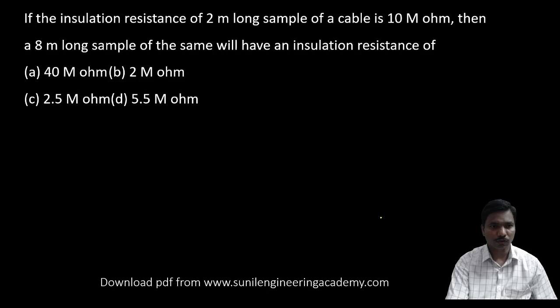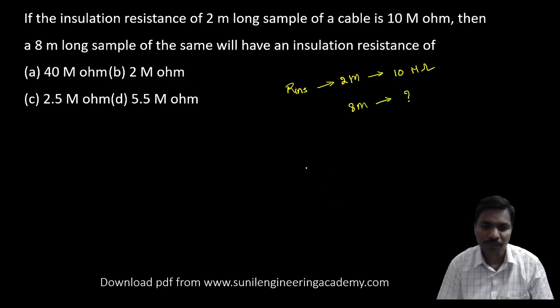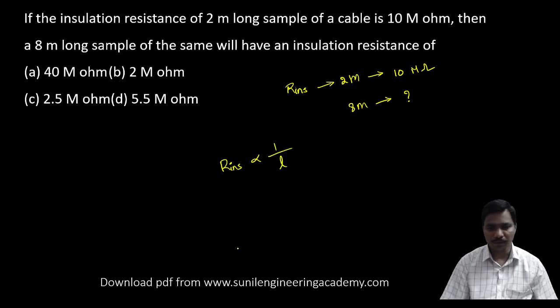Okay, coming to the next question. If the insulation resistance of 2 meter length is 10 mega ohms, then an 8 meter long sample has an insulation resistance of dash. We know very well insulation resistance is always inversely proportional to the length.